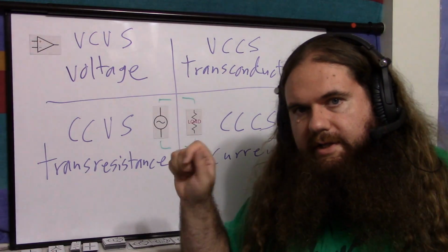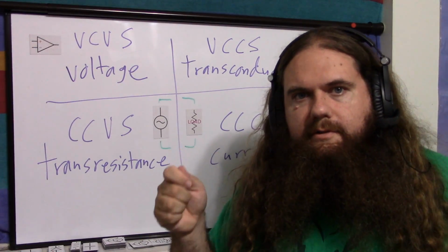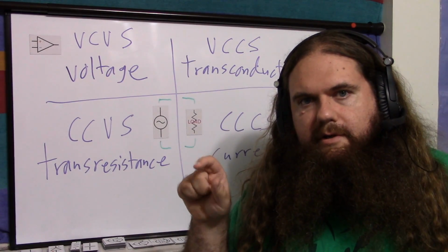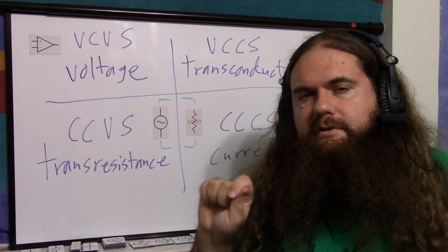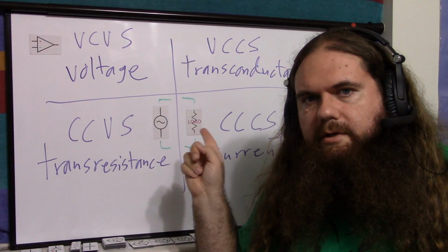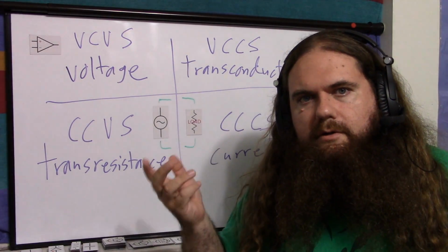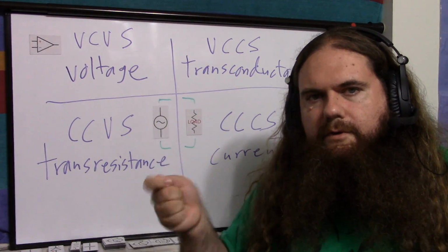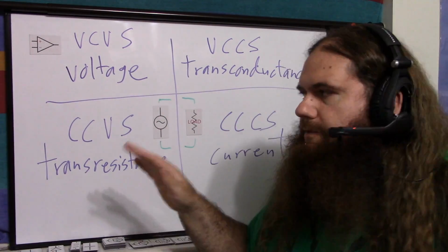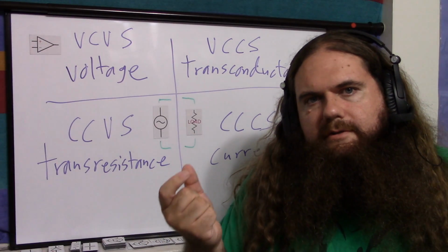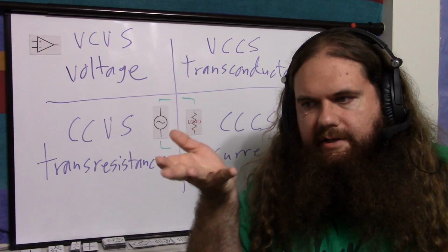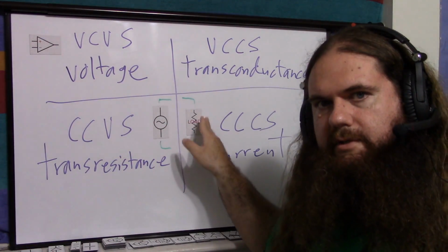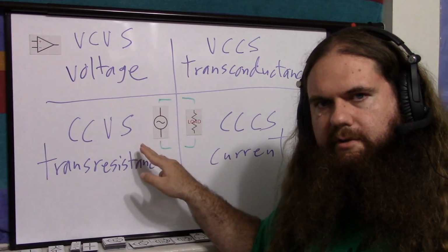So let's say you have a potentiometer, a variable resistor, and you hook it up to an op amp, you're going to have a certain voltage across that variable resistor. If you change the value of that resistor, if you turn it up and down, the voltage across it will not change. V equals I times R, Ohm's law. If R goes up, I goes down to keep the same V. So the current is changing, the voltage is not, so it's a voltage source. That's the conceptual thing. You don't think of voltage or current as an output as in here's current on a plate, here's some current. It's that the output applies a voltage across the load proportional to the voltage in.